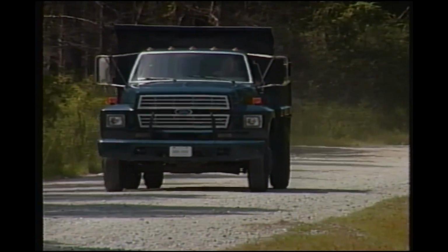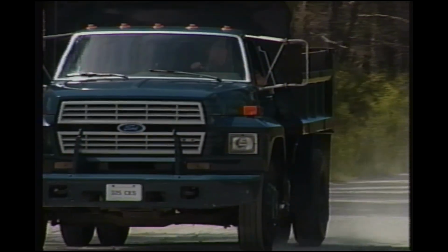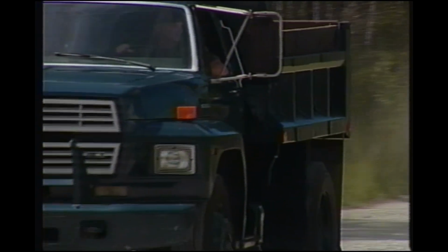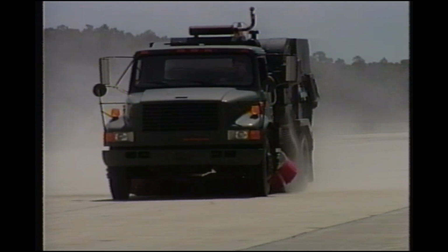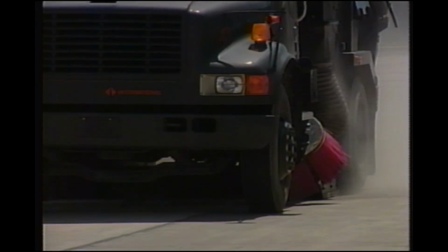This lever is often overlooked after material has been dumped from the bed. Frequently, the truck will be reloaded and the operator will head back to the construction site only to leave a trail of fresh material following behind. Failure to lock the tailgate in the closed position often leads to unnecessary cleanup work.